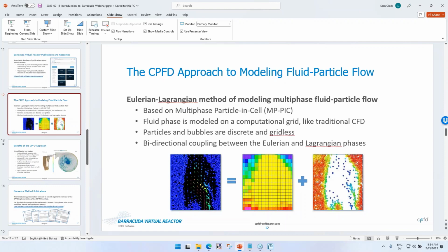We're tracking all these properties for the cloud, and then we calculate the physical changes that the cloud would undergo in terms of position, velocity, acceleration, and composition. Then all of those changes are assumed to be applied to all of the particles represented by the cloud. It's almost like an inverted approach to what people do with CFD models. Typically the CFD model subdivides a big space into little boxes, and we solve the equations on the little boxes. What we're doing now for the parcels is grouping a bunch of physical particles into a cloud and solving the equations for that cloud.